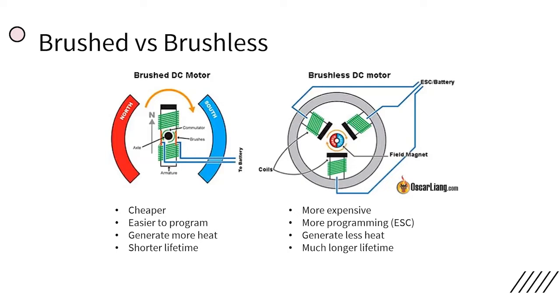So in many instances, you'll find that when looking at other robotics projects, brushless motors are starting to replace brushed motors. But as long as you aren't concerned about the lifetimes and you have a brushed DC motor that will satisfy the speed requirements you need, a brushed DC motor will usually work just fine.